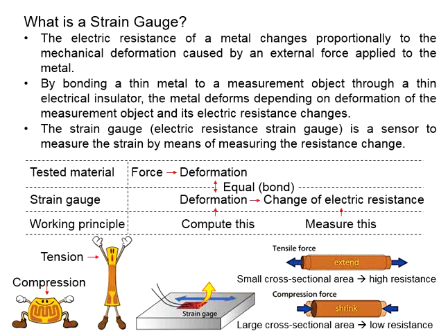In contrast, if the strain gauge is subjected to compression, it becomes shorter and fatter. The electric wires or foil will undergo compression. It shortens longitudinally and expands sideways in the lateral direction. This leads to a larger cross-sectional area. And when the cross-sectional area of the wire increases, the electric resistance reduces.